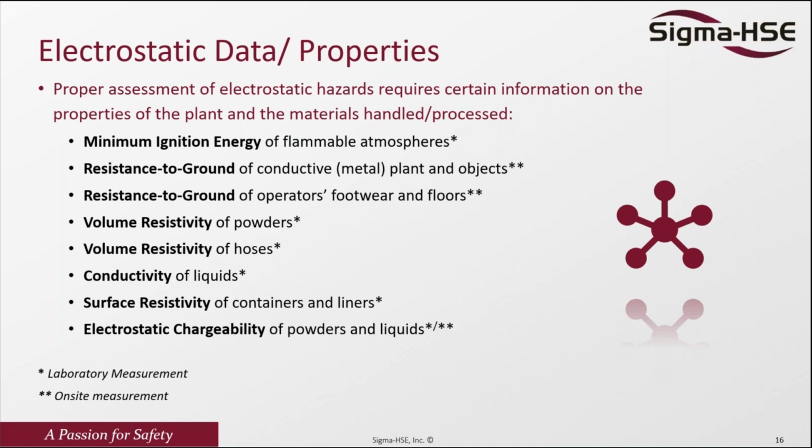I also need to know the surface resistivity of the material that you are using, whether it's a container, whether it is static dissipative or maybe insulative. And I need to also know chargeability, in case the material travels in a hose or in a pipeline, where the material collides with each other and starts to charge. So I need to know this chargeability. These are some of the key parameters I need to know in order to perform an electrostatic hazard assessment and assess the risk associated with your operation.